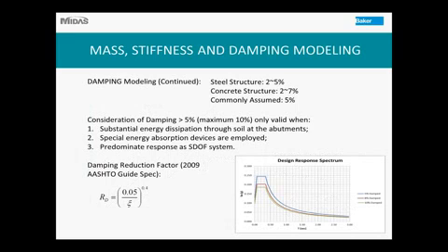Instead of going through all those damping calculations, people usually just assume, for steel structures, a recommended 2 to 5%. For concrete structures, it is recommended to be 2 to 7%. The common assumption is 5%, and it's really hard to argue with that 5% assumption. That's become what we need to do. So the response spectrum recommended by the code is based on 5% critical damping.